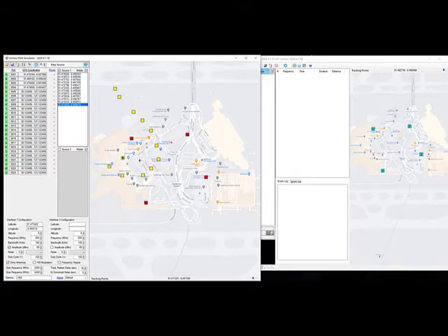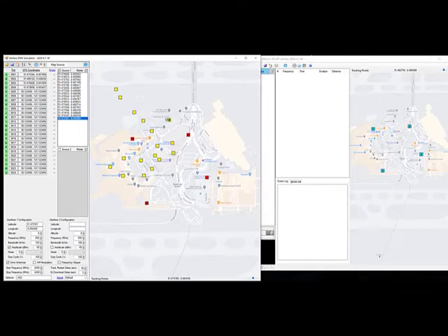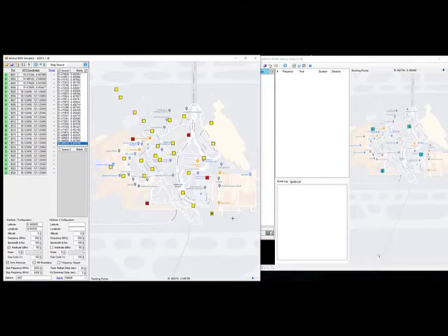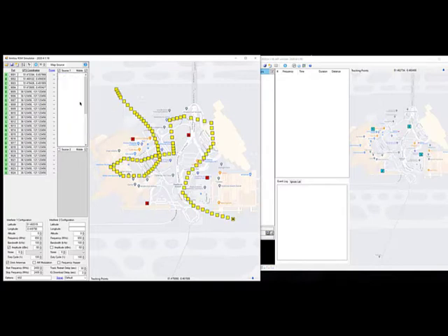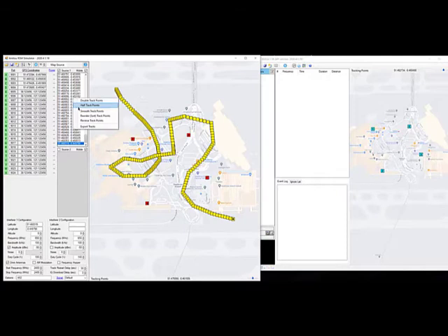You can also perform some worst case analysis by moving the drone path perhaps outside the network or far away, and see how the AeroShield software performs. So now that we have our path, we can right click in this area right here, and we could double the drone points. We can also smooth it out a bit if we want, so it's arbitrary how we'd like to do that. Each GPS coordinate will show the precise drone position as we go through the map there.